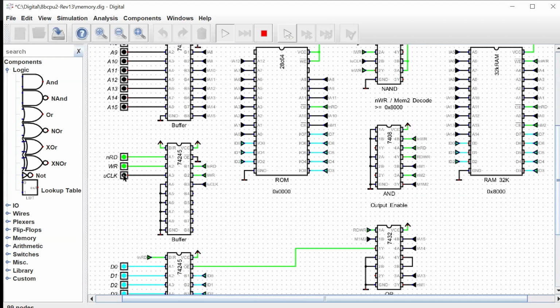So that's the issue. Just like here, as soon as the read signal goes low, the data bus goes active. We really want that same behavior. When the write signal is raised, we really wanted the data bus to go active, but it's not. It's waiting for the U clock. So that's the error. So what's our remedy?